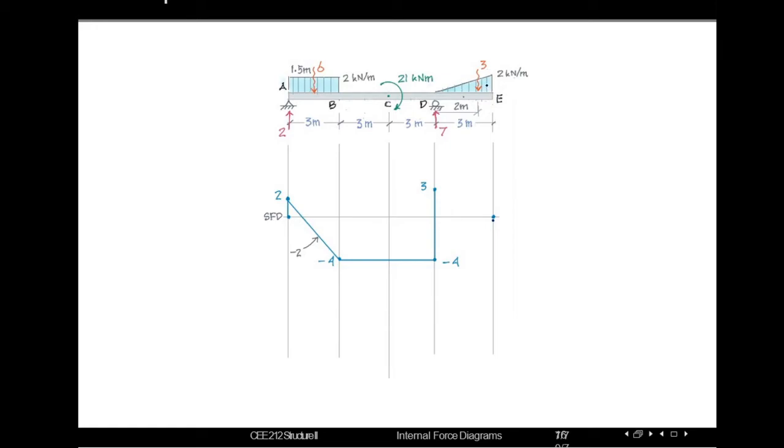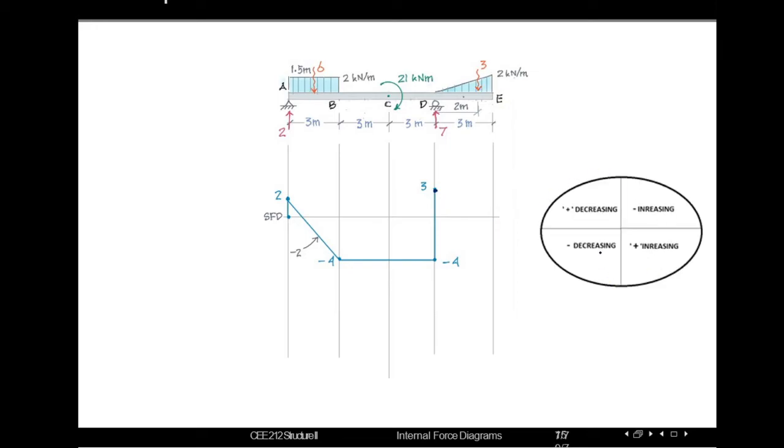So as we know, if the loading is triangular or the area is triangular, the line, for shear force or bending moment, will be curvilinear. In all cases, if the loading pattern is triangular or the area is triangular, whatever we may say, the line will always be a curvilinear one. So we know there are 4 types of curvilinear lines.